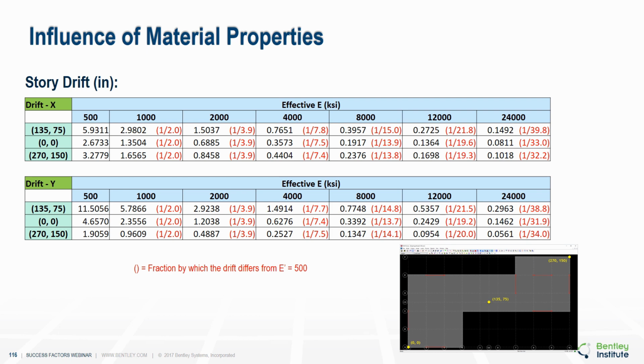Remember that this model has a very soft diaphragm. It has a steel deck that's only 0.0199 inches thick, which is the gauge of the deck. What we see here doesn't pertain to concrete slabs or composite slabs because they are so much stiffer. They are way off to the right of this chart. The contribution of the deck deformation to the overall drift is so small that it's inconsequential for those decks. What we are seeing here is only an issue for decks such as bare metal decks.